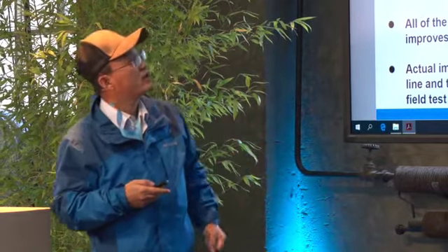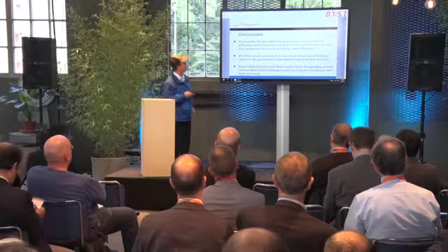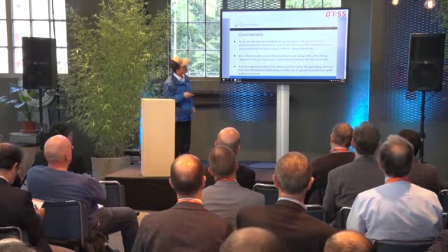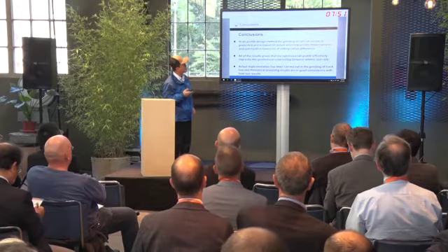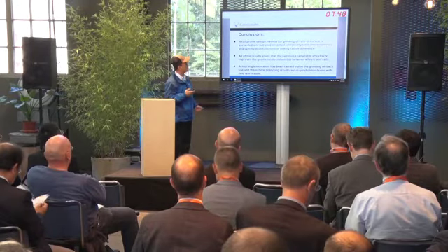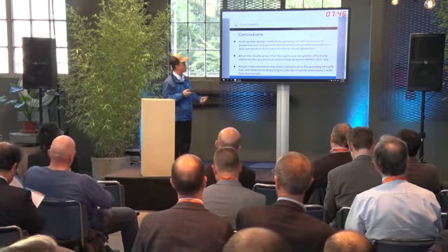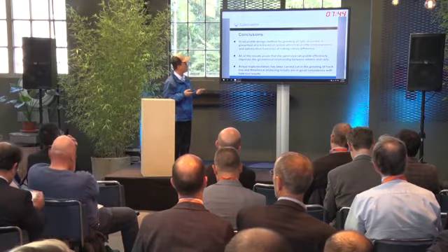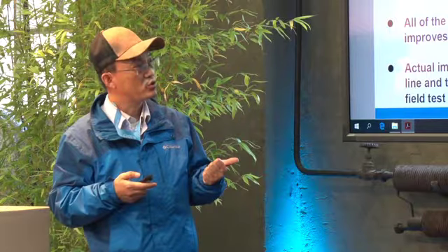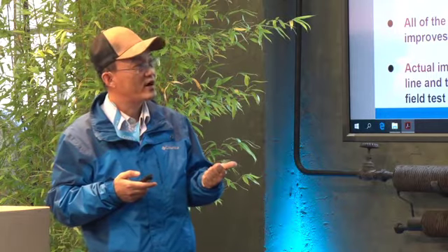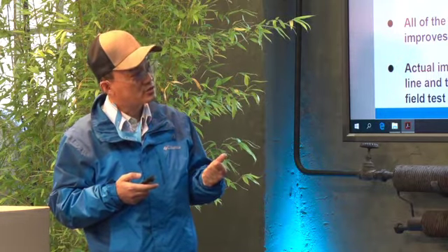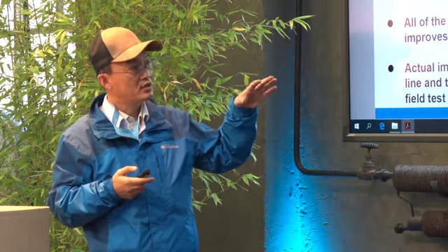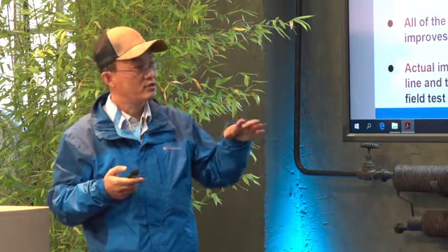Okay, and now we have conclusions. A rail profile design method for grinding rails on curves is presented, based on actual wheel-rail profile measurements and the optimization function of rolling radius differences. All of the results prove that the optimized profile effectively improves the geometrical relationship between the wheels and the rails.